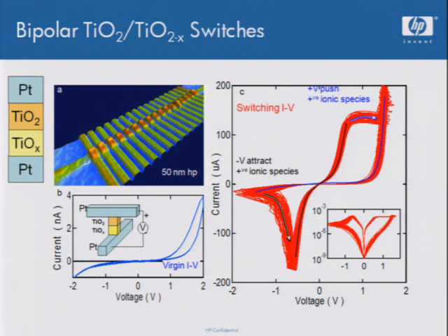So we're going back and forth between two end states, but in fact the switching itself is continuous. This is not a binary switching event, it's a continuous switching event. And we can stop the process at any point in time and have any intermediate state between a fairly low resistance, thin barrier tunnel region and a Schottky barrier.